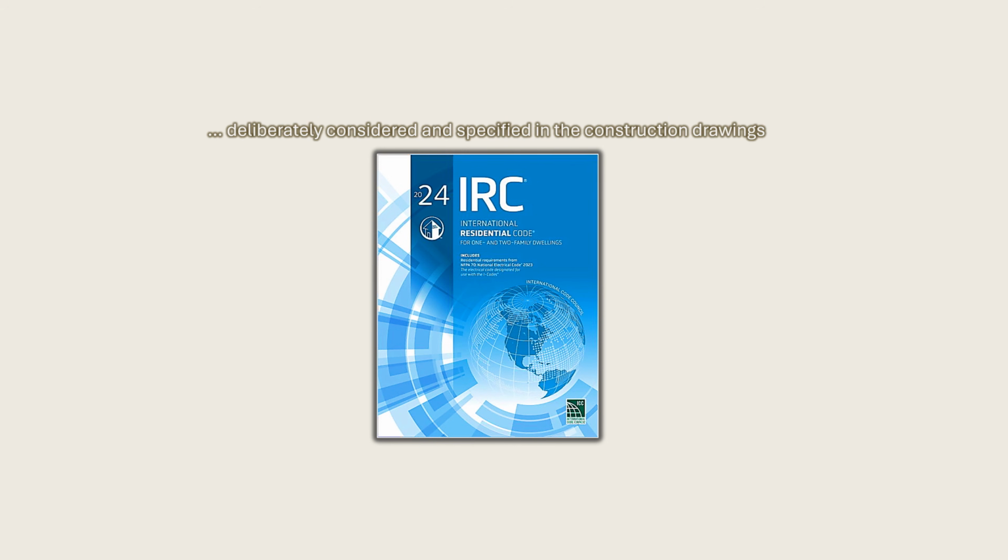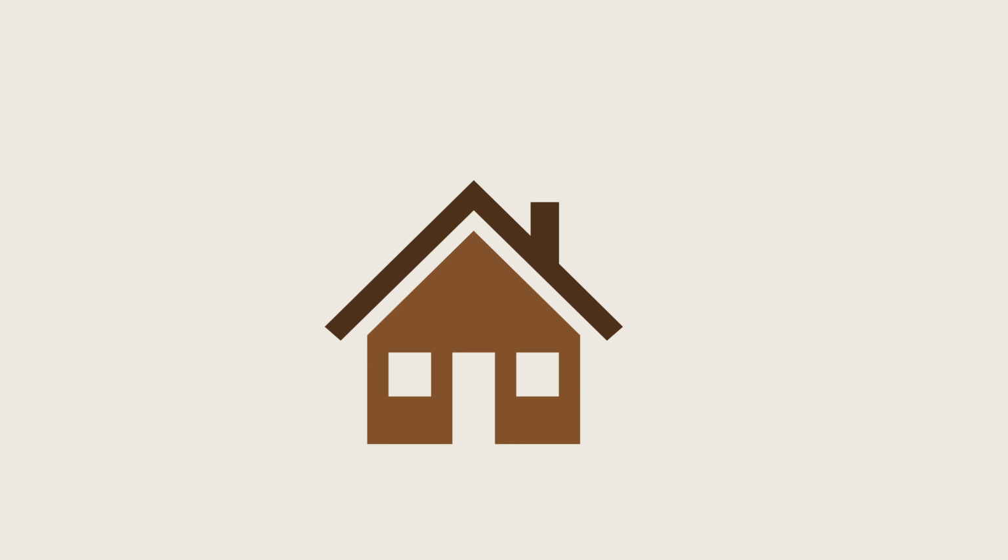Therefore, as we have seen, the type of nails that you use in residential construction is neither a trivial issue nor a mere afterthought. This is a critical factor that must be deliberately considered and specified in the construction drawings to ensure code compliance and structural integrity. Additionally, the contractor must ensure that the nails used in construction are consistent in type and size to the nails specified on the construction drawings.